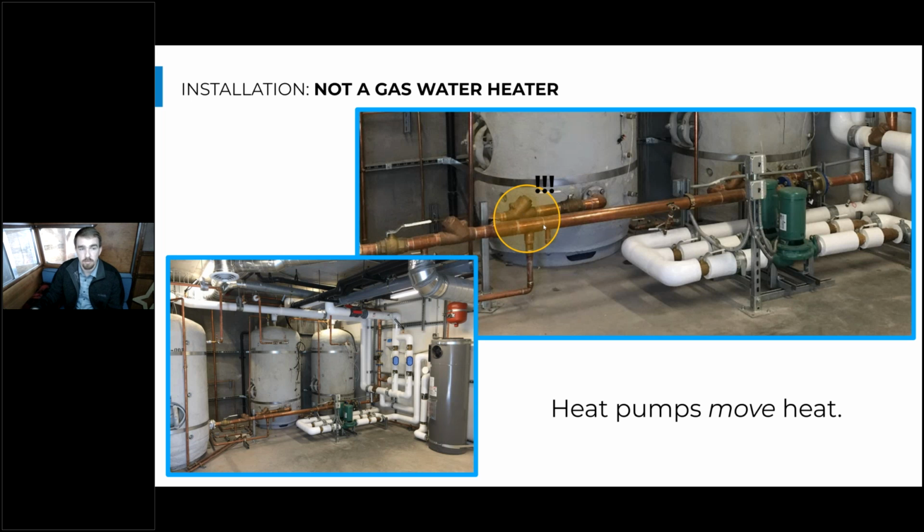So if through a best practice, the plumber threw in this check valve, now the heat pump can't pull that cold water out of the tank, and so it won't see flow when it tries to run, and then it will go off on high pressure. So that's one example of a best practice that works really well and a lot of times isn't in the drawings, but is added after the fact, that should be talked about with the engineer or the rep before it's applied if it deviates from the drawings at all.